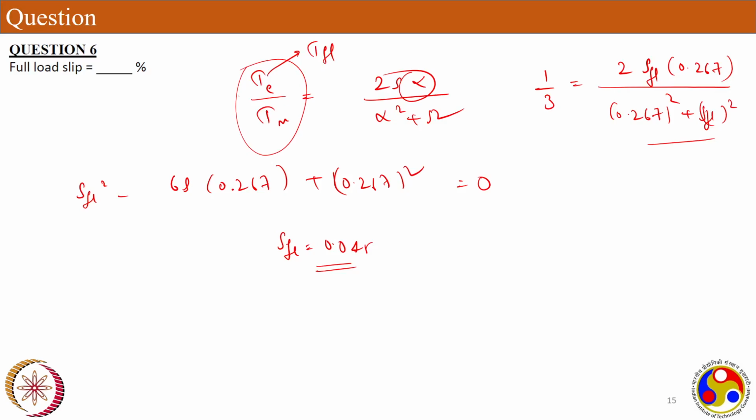Yes, torque will reduce significantly. That's the disadvantage we have seen. So your motor will not be stable. Not stable means it will work, but in very poor condition. You can't have a good torque profile, you can't have good flux also. But your speed control you can achieve. That's the downside of controlling speed above rated speeds. You have to increase the frequency and your flux will go down, and your core won't be magnetized well. You won't be able to use the machine because your machine is capable of giving that maximum torque, but you are never going to use it.